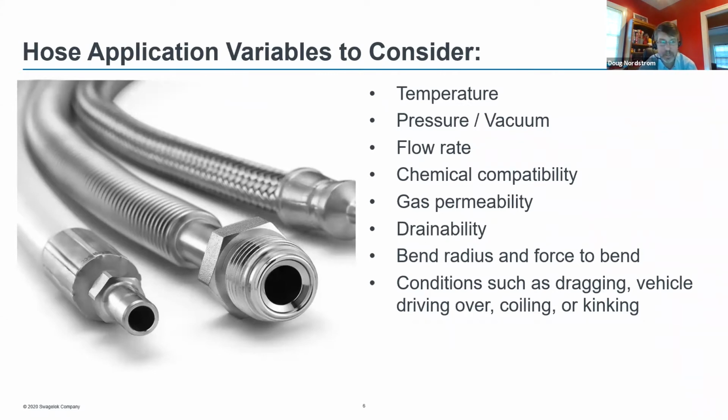It's a very different aspect. Likewise, some hoses have a large bend radius. They kink relatively easily, but you can get that bend radius very easily. They bend very, very easily, and what this causes, of course, is a very kinkable hose, because it doesn't take much force to create a bend radius that's going to cause a kink. So these things need to be considered and looked at when selecting the right hose.